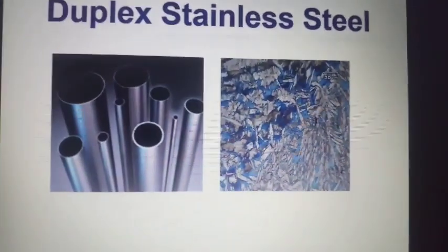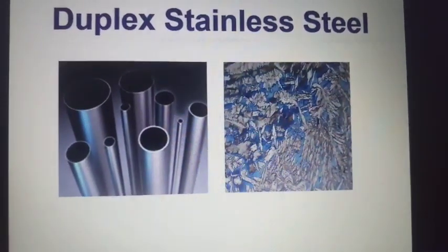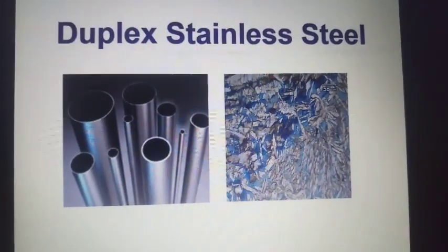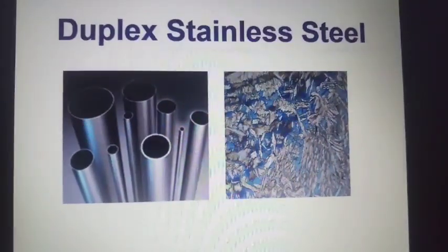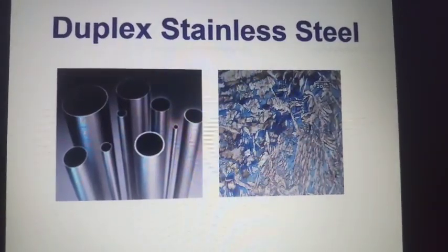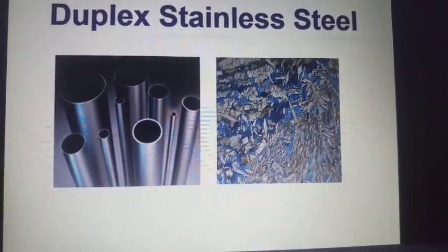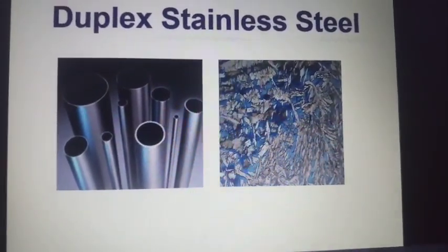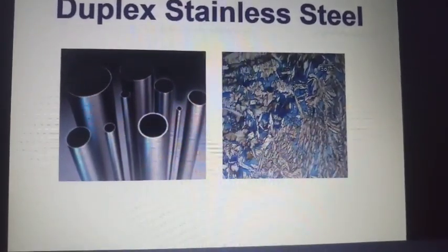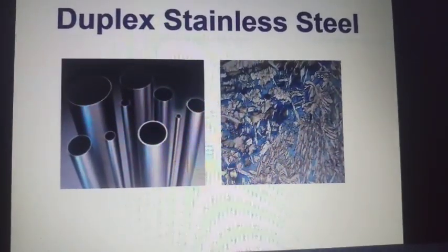Interpass also should be close to room temperature, around 50 degrees C or like that. It is better. And then weld the smaller beads so that you end up having a faster cooling rate, and then you don't have sufficient time for the 800 to 400 transformation. So between pass to pass they have to give a gap. Yes, and smaller passes.